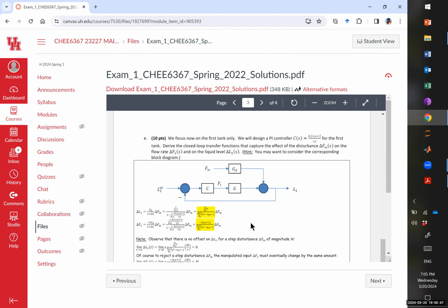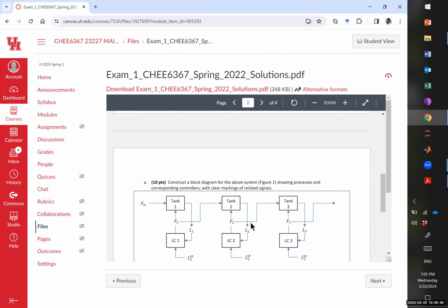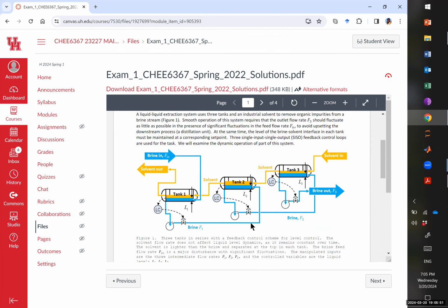This, by the way, is from a very real process with a company where I had a student who interned, and they had this very problem. Interestingly enough, the engineers figured it out heuristically after a long period of thinking how to redo the whole thing. It sure seems like just doing a feed forward controller based on the FM would be the easiest thing, but that's not part of the problem. It's not simple, because if you only do feed forward, you mess up the downstream part. So it needs some thinking.